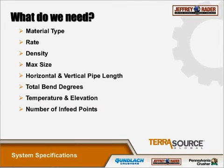You need to know the number of in-feed points. Typically, you'll have one in-feed, but you can do multiple injection points. In this case, we do need to know the exact location of each feeder, since there's going to be different rates delivered at each location, and that is going to be an important factor for us.